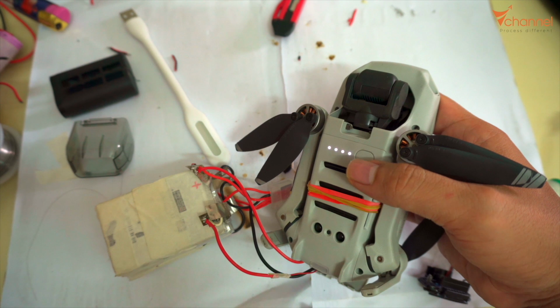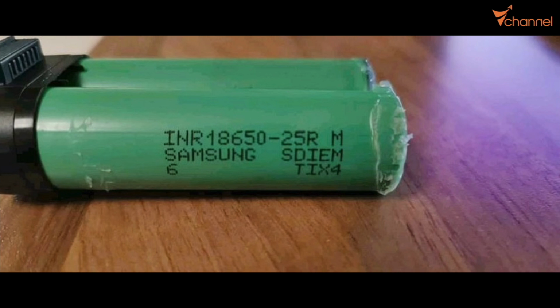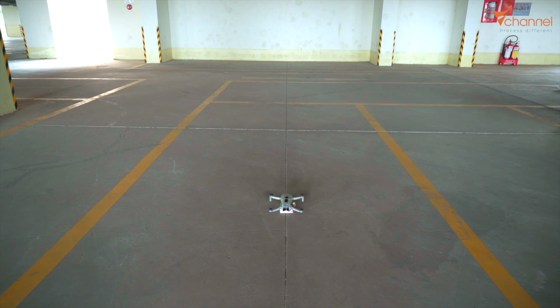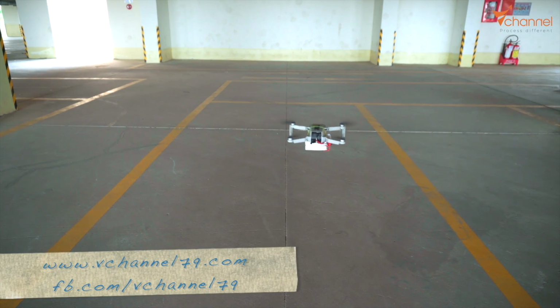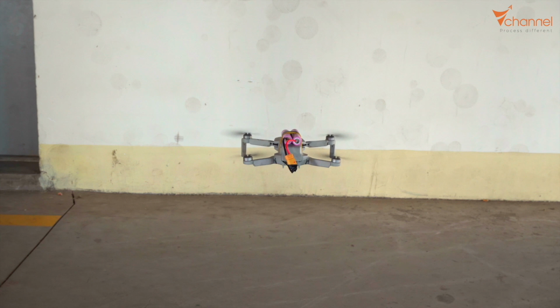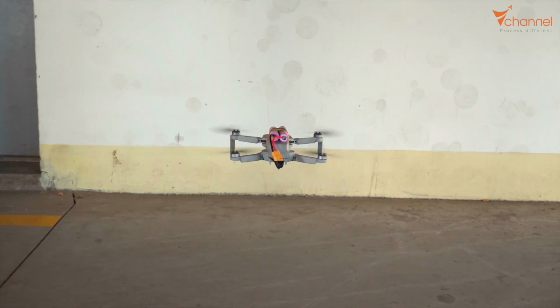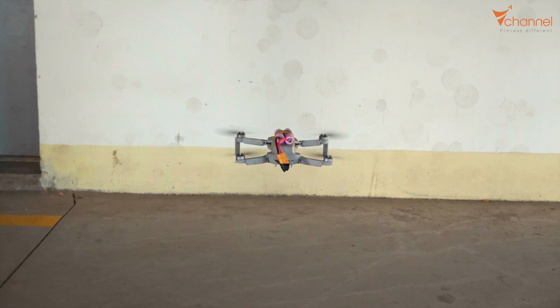In the case of the Mavic Mini, the original cell, that is the Samsung 2400 mAh, has a discharge rate of 20 ampere. So we must find a battery with a suitable discharge rate, and the best is equal to or higher than 20 ampere. And now, I will modify with many battery cells, both lithium-ion and lithium polymer, by parallel and series connection. We will see the result and what is the best solution for the Mavic Mini.